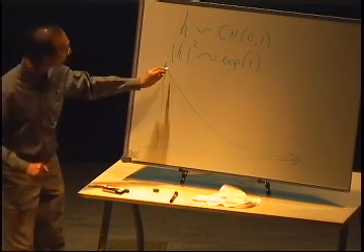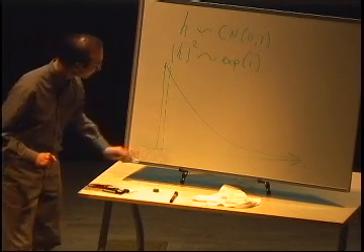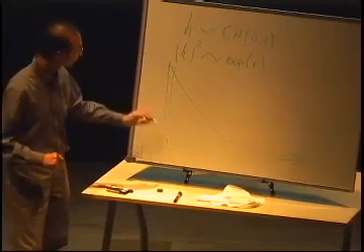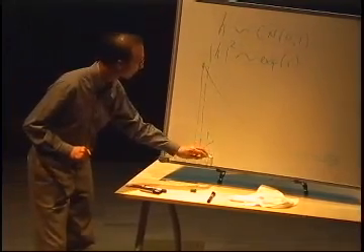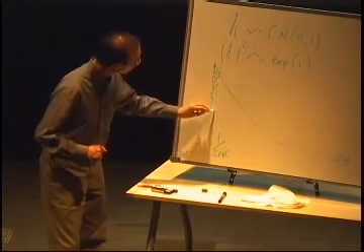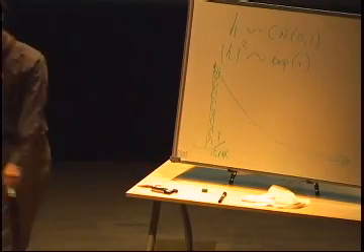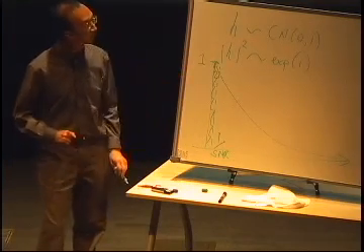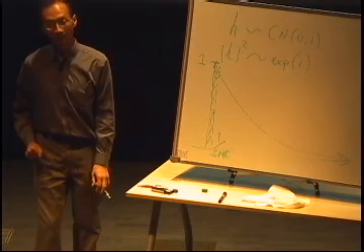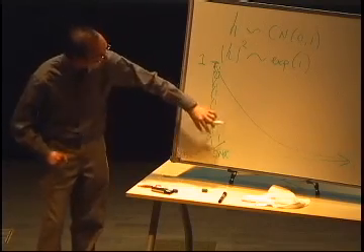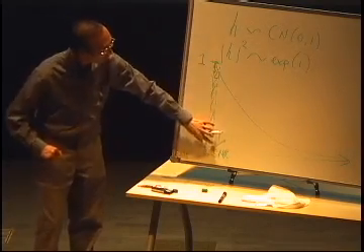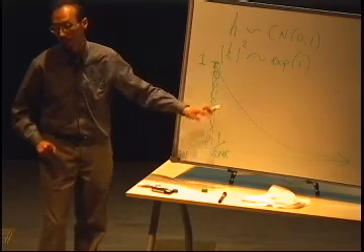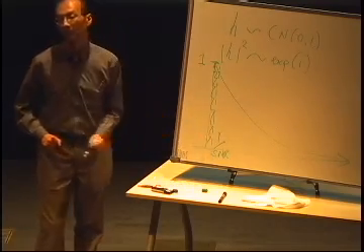Okay? All right? Now, the probability you're in a deep fade is when this channel, h squared, is less than 1 over SNR, the threshold. So the probability is this area. So you can see that this height for an exponential random variable of mean 1 is 1. So the probability of this is the area of this. And for high SNR, it is essentially 1 times the width, which is 1 over SNR.